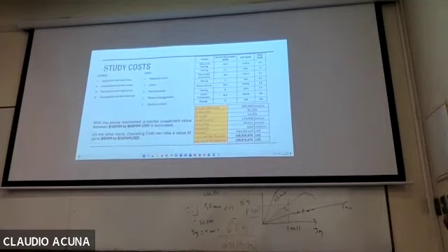I just explained today how to do the scale-up, so just in case, review whatever numbers. I did the following exercise. I took the 800,000 tons per year divided by 8,200, which is the operational running time. I don't know the solid content. I know it's fine particles, so it will be 20% solid in the best case scenario. Then you have the total amount of pulp. I don't know the density, so I assumed a number, 1.3 tons per cubic meter. Then I end up with cubic meters per hour: 375 cubic meters per hour. So it's going to be big.